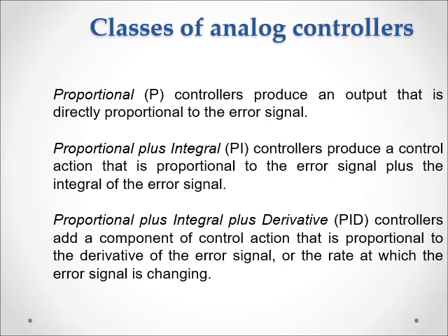When you have an error, you multiply this error signal by a gain value using an inverting or non-inverting amplifier. You can adjust the gain, and the error is multiplied with the gain and causes a voltage or output which is proportional to the error signal. Accordingly, if the error is high, the actuation effort will be higher, and so on and so forth.